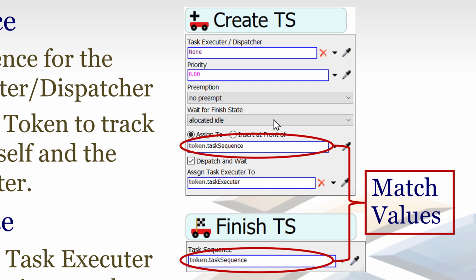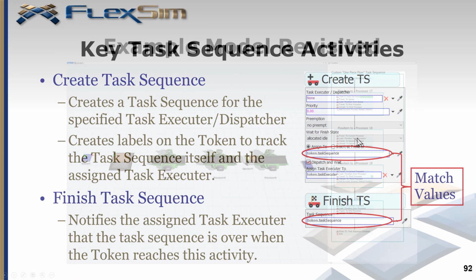If there are delays that don't put the task executor into a state natively, then this is the reporting state the task executor will be in until another task puts it into a state. This will count towards the default utilization calculation on the dashboard, so it's important for meaningful utilization reports.